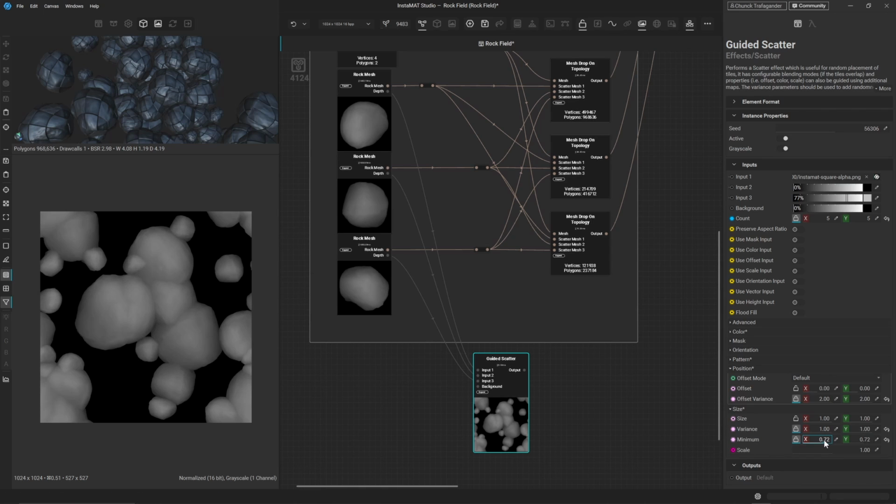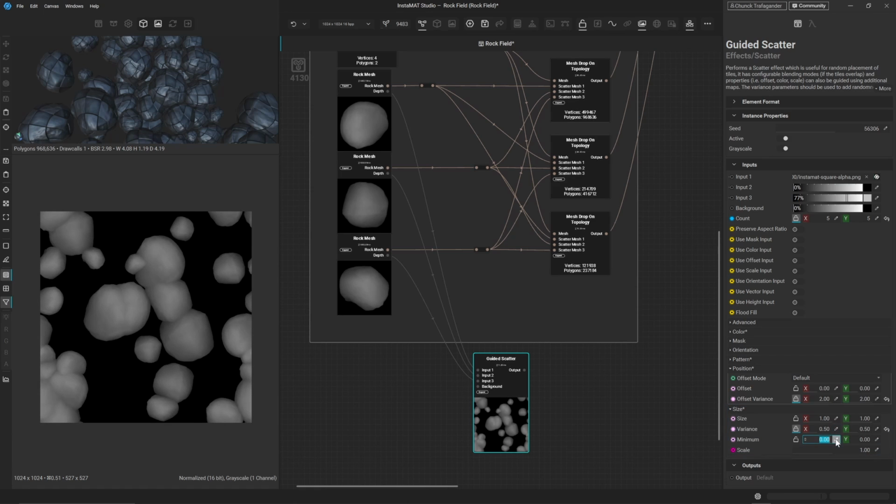So it essentially sets a clamp or a cap at the bottom value, which is really useful because a lot of times when you use this random slider in really any application with a randomness value, it oftentimes makes things way too small when it comes to scale. And then it's a bit of a battle trying to scale it up and then playing with the randomness and then scaling it up. It's just a lot of back and forth. So this is really useful for our application here. And I think in my testing, I set a value of maybe 0.4, just in case anything got smaller than that, but I don't think anything sized up. So we should be good to go.